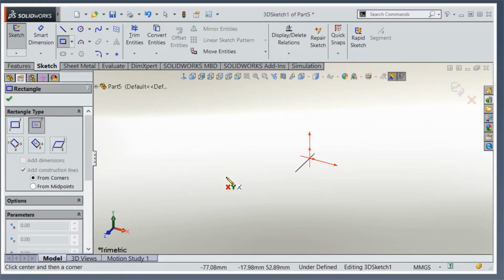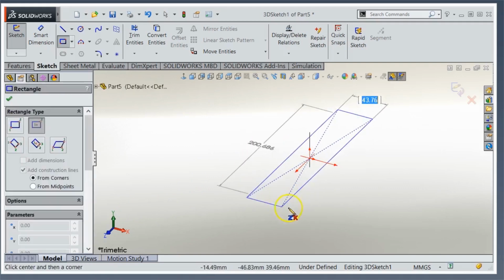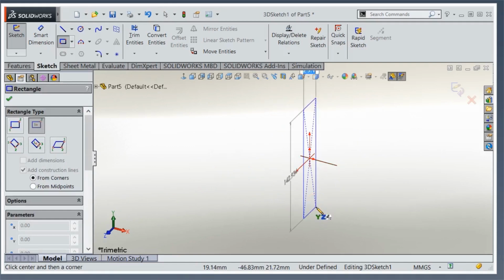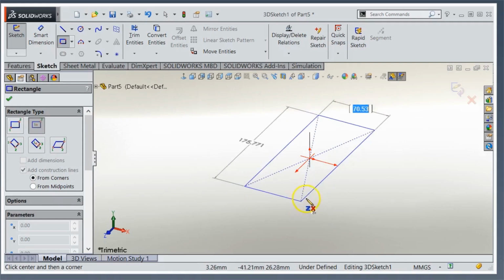of my frame. Right away, I'm going to see my XY appear under my cursor. That corresponds with the triad down here, along with the red axes you see right where the origin is. If I hit Tab, that'll actually change the orientation that I'm looking at. So for example, if I'm drawing a rectangle, like I'm going to in a minute, if I drag it out, I'm in the ZX plane right now. Hitting Tab will actually flip that 90 degrees, depending on which orientation I pick.